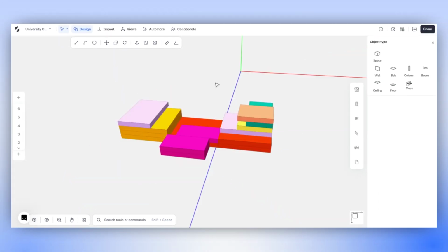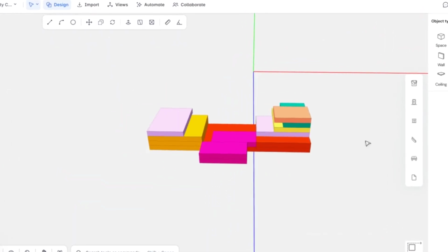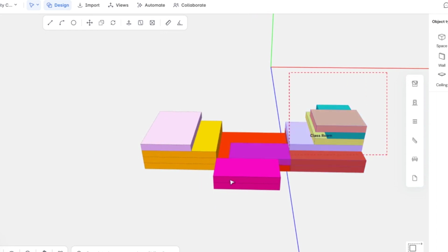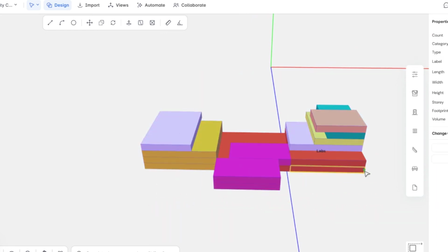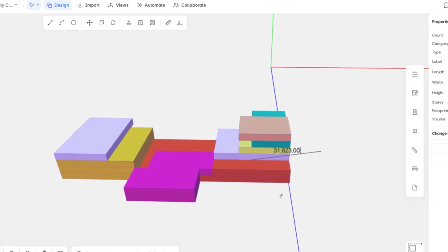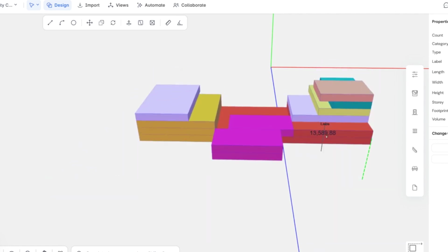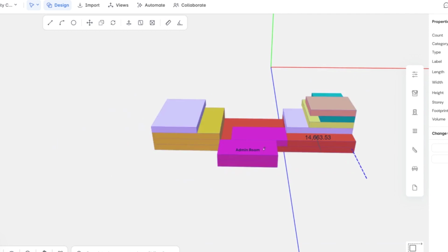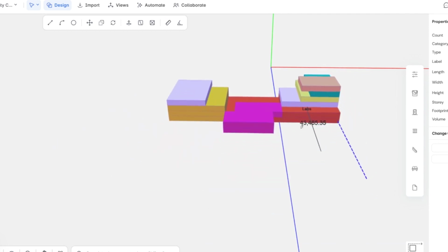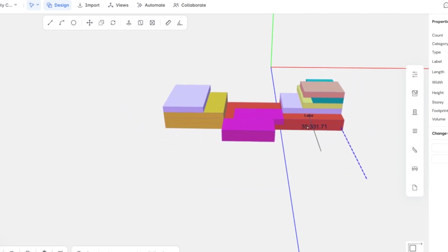To move multiple objects together, multi-select the objects you want to move. Then, left-click and drag to move the selected objects together. To make more efficient use of this feature, lock the axis using the arrow keys on the keyboard to restrict the movement direction.